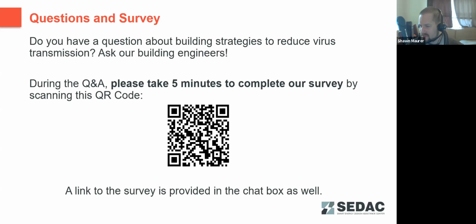Are we familiar with a system that uses bipolar ionization in conjunction with UV lights in the room, in light fixtures, when the room is occupied? Yes, we have seen systems for in-room air purification that mount on the ceiling, and they have UV lights built into them, or ionization technologies, or both. They are somewhat expensive to install, but they are available out there.